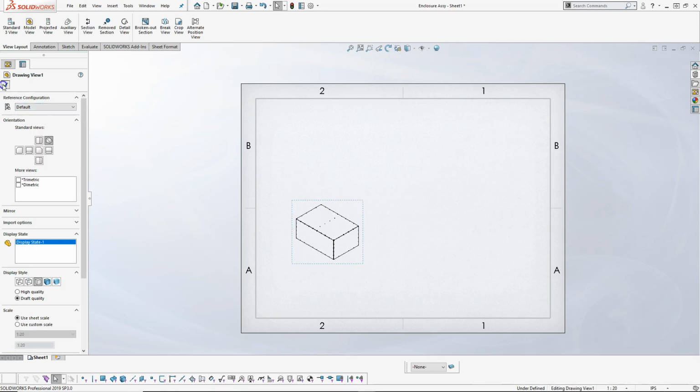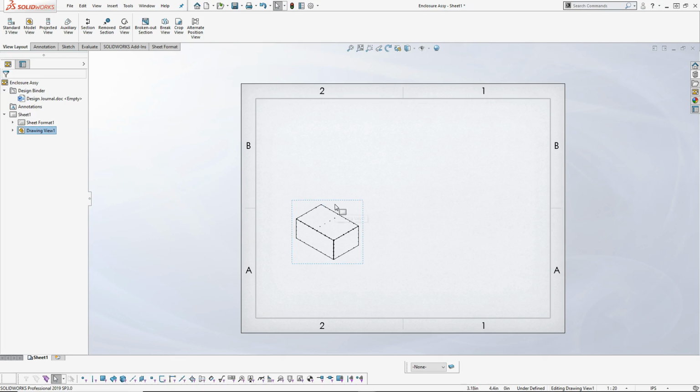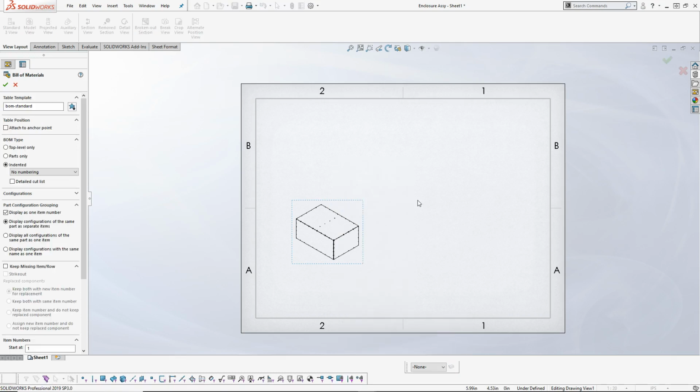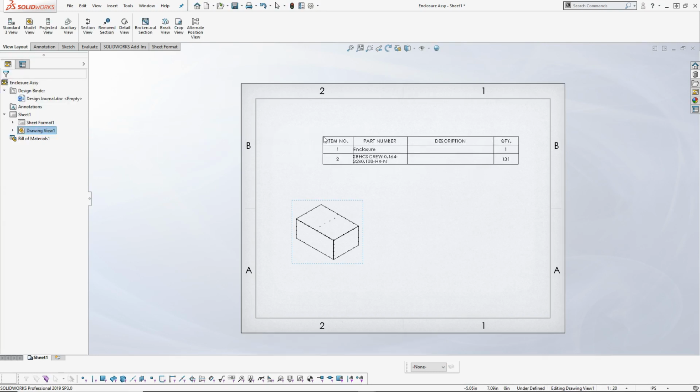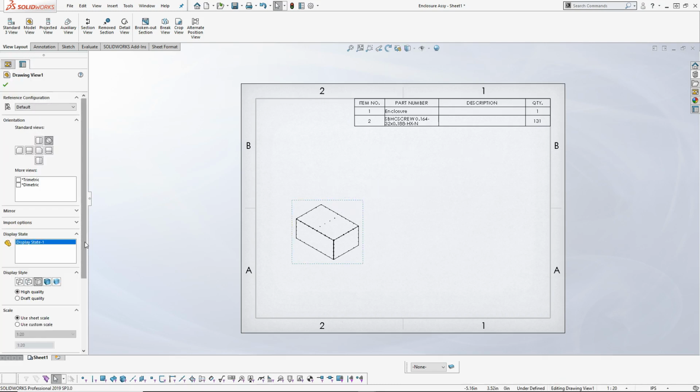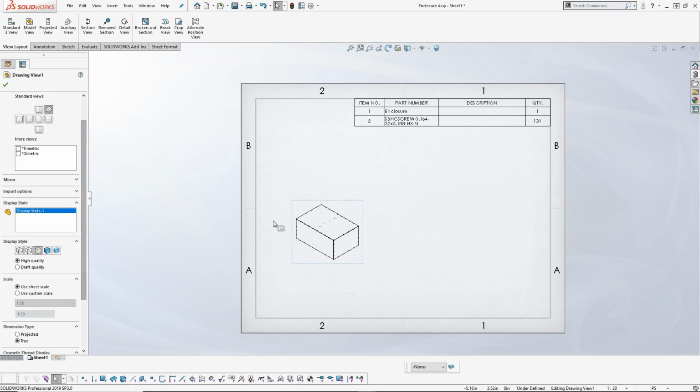And going through this process, then when I create a bill of materials, tables, bill of materials, I really should only have 2 items, so let's just go top level only. And 131 screws. So we're going to be a little busy, and I miscalculated. I was going to order a box of 100, so I'm going to need a few more boxes of those to assemble it this way. Still think that's going to be cheaper than trying to weld all those seams.